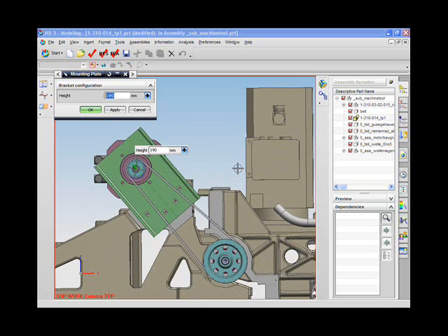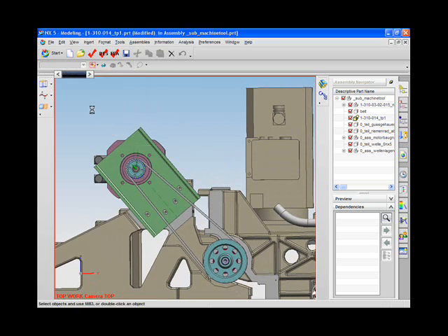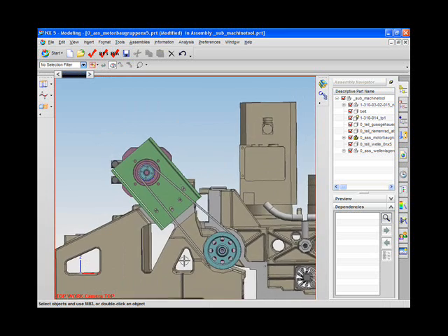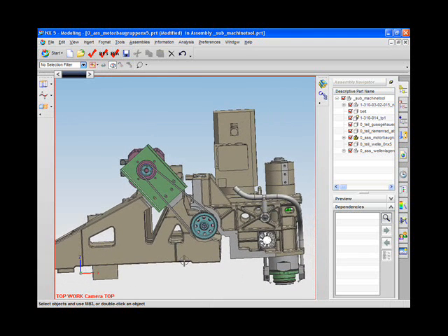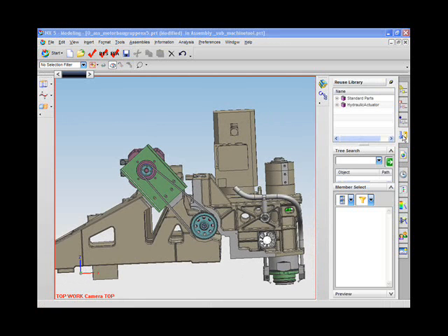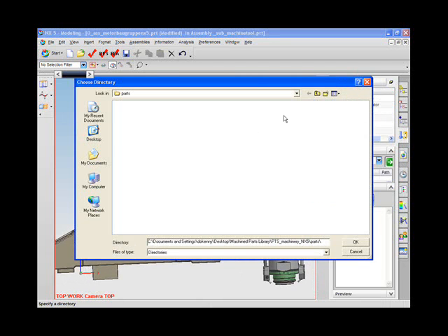And so this is something that's very powerful for reuse, and one of the things that makes it even easier is that you can place it inside a reuse library. So for example, if I go to the location where the bracket template is stored, I can go ahead and add this to my library. And so if we come in here to the machine parts library and we go to our templates file, you'll see that the mounting plate is available for everyone to use. So anyone who has access to the reuse library will be able to use this part.